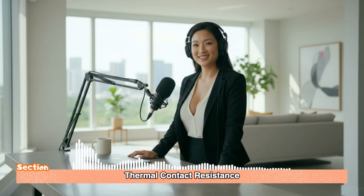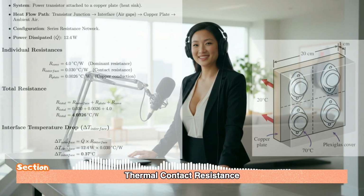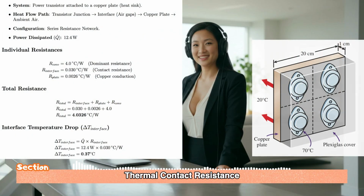The sources have an example of a power transistor attached to a copper plate. Transistors get hot, and they need to dissipate that heat to survive. So we analyze the heat flow. It's generated by the transistor. It has to flow through the interface, then through the copper plate, and then finally convect to the ambient air. It's a 3-resistance series: R interface plus R plate plus R conv.